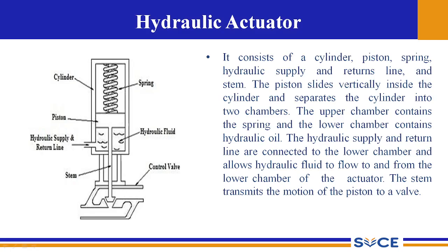So you can see that there is a cylinder with a spring and a piston arrangement. The hydraulic fluid actually moves the piston up by interpreting the control signals. So depending upon the control signals, either this piston moves up or the hydraulic fluid is compressed so that this stem with the seat of the valve stays at a particular position.